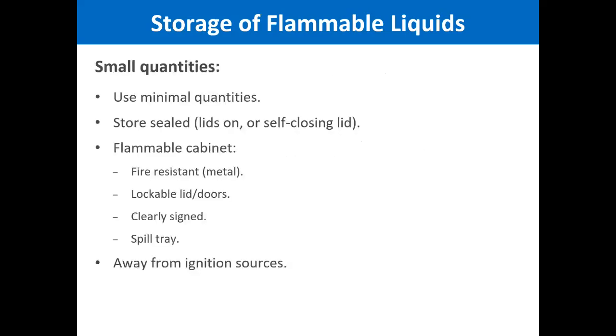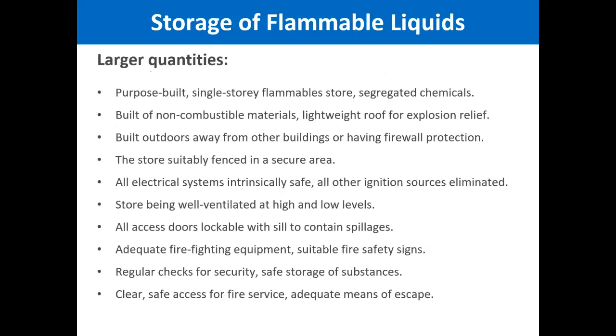Okay, so, always use small quantities, use minimal quantities. The store should be sealed properly. The flammable cabinet should be fire resistant, with lockable lids, and clearly signed. Drip trays should be available as well, and it should be away from the ignition sources.